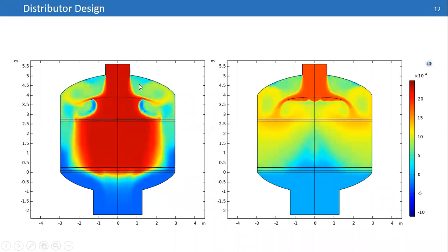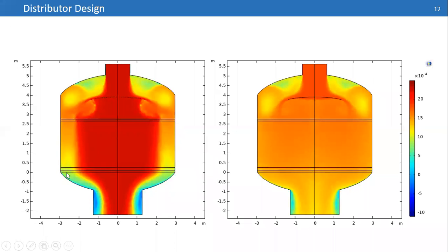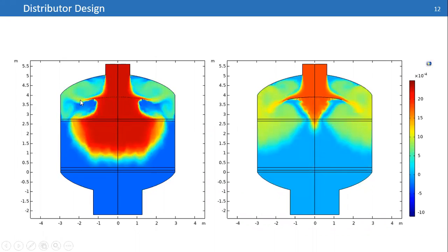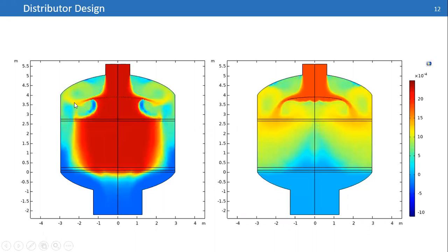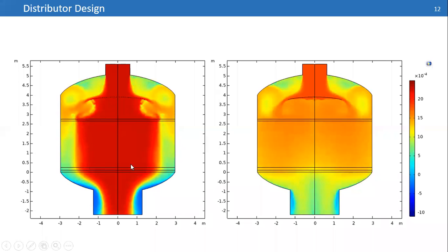For the case of this system, the one point that I just want to mention again, you have different domains. Here is free. Here are the ceramic balls loaded for support of the bed, and here is the bed support. And you solve Navier-Stokes in this domain since there is no catalyst. You solve the Brinkman equation for this domain, and you solve mass transfer since you have a tracer.